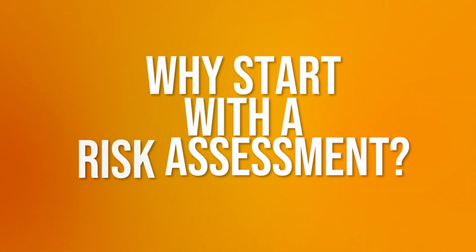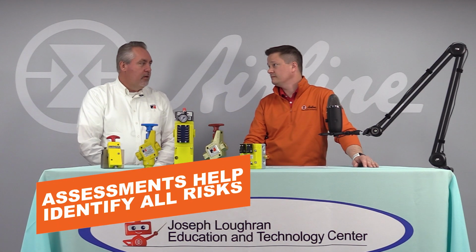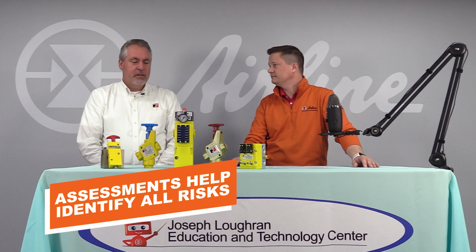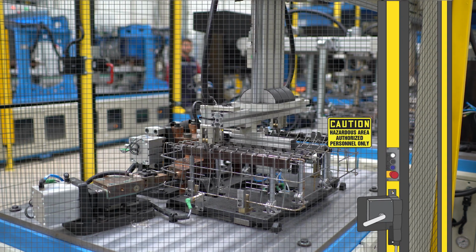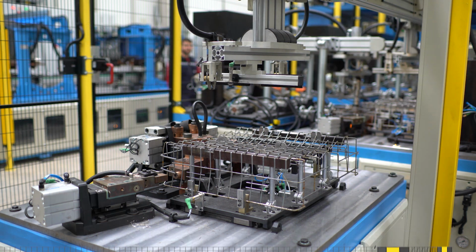So why should a risk assessment be the starting point? Well, if you don't do a true assessment, you may not identify all the potential risk. An example from one of my customers: they saw a hazard, they went out and put a safeguard in place immediately without doing an assessment, just to find that the guard had been removed a couple of days later. They asked the operator, why did you remove the guard? Well, I couldn't do my job. A risk assessment would have identified things like that.